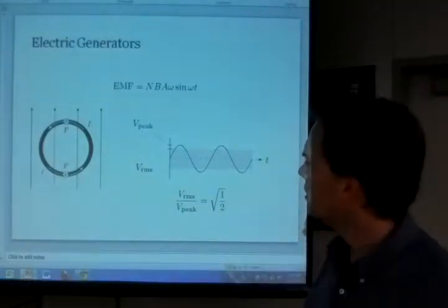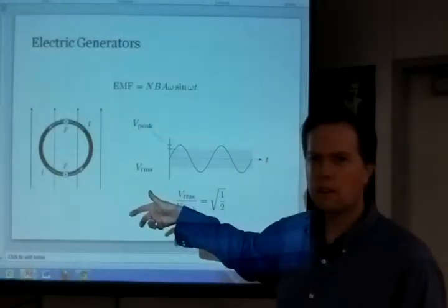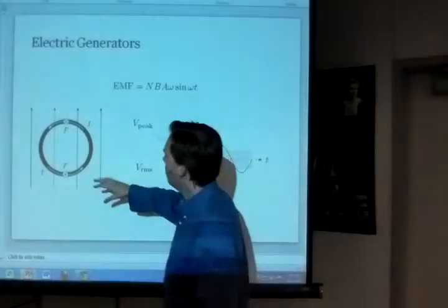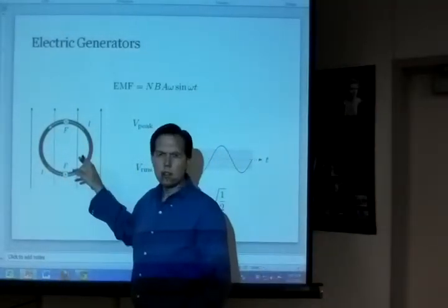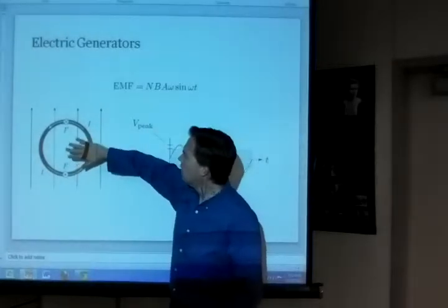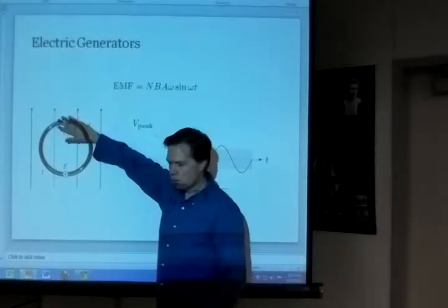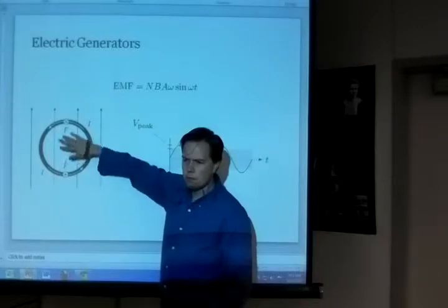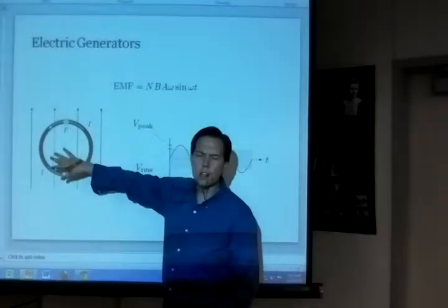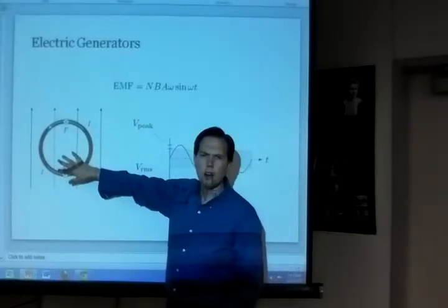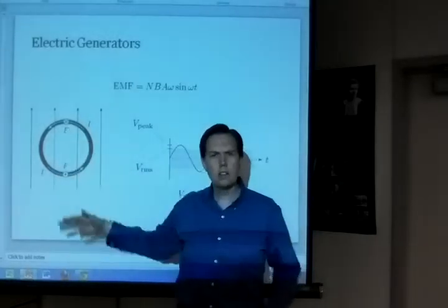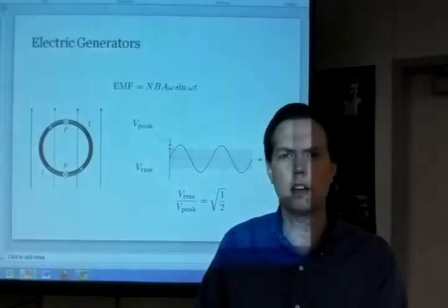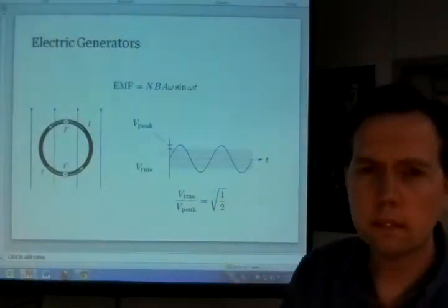And by spinning it across the magnetic field like that, you generate an electromotive force inside the ring, because essentially when the ring is in the orientation that it's pictured right here, there is no magnetic flux, because the magnetic field is exactly parallel to the area contained inside that ring.